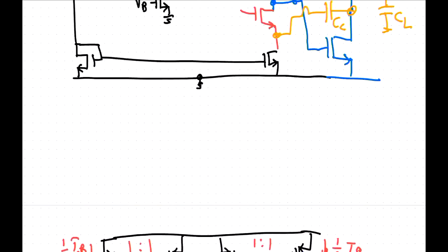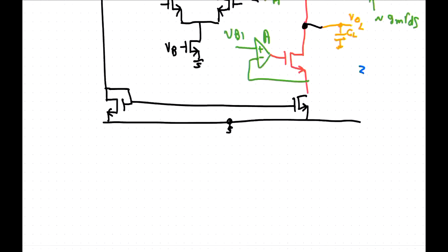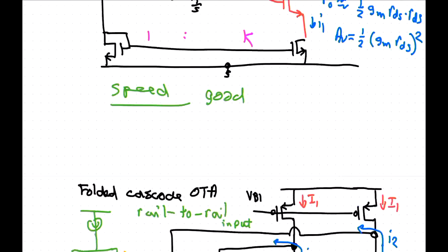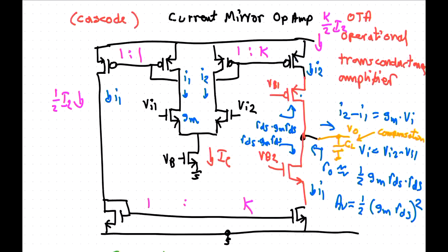Now if you go back to this circuit here, we have something similar, but if the current up here is larger than the current down here, so we have a current flowing out here, then it pulls down like that. Effectively that gives us an offset output current.